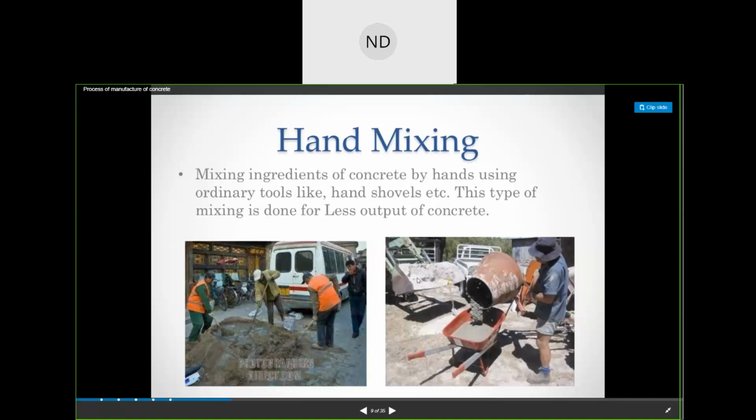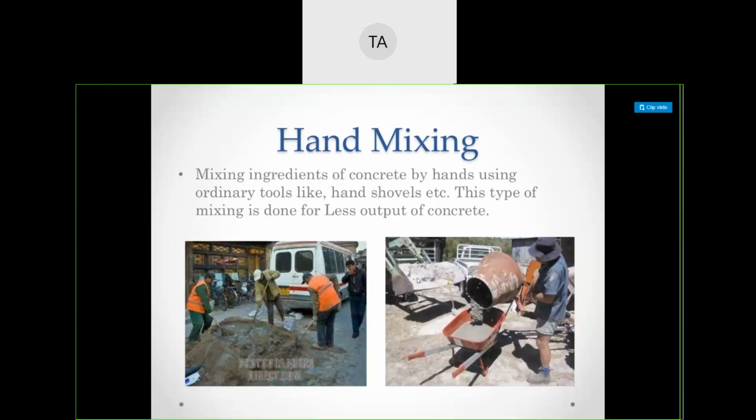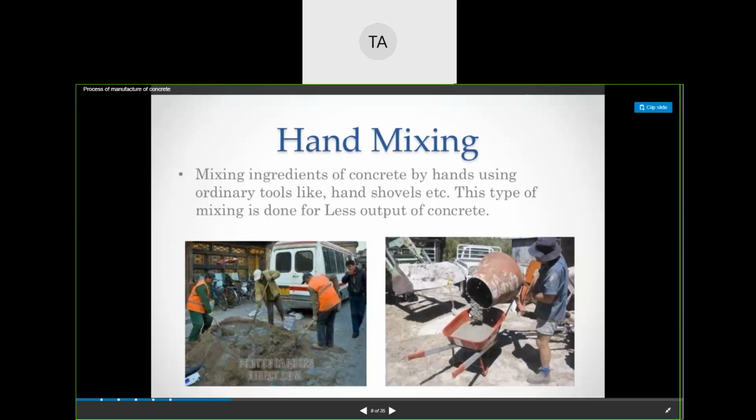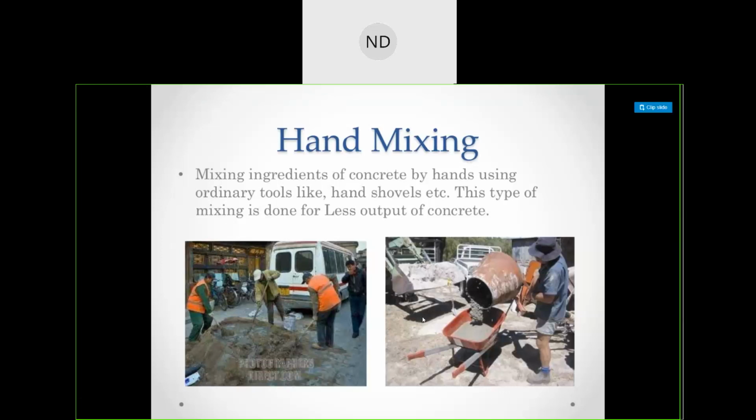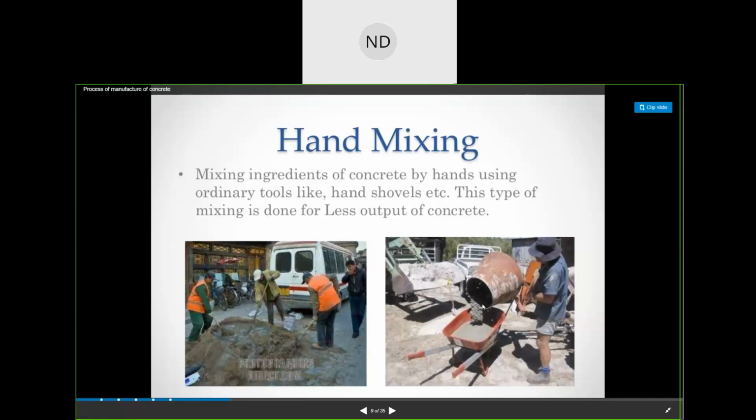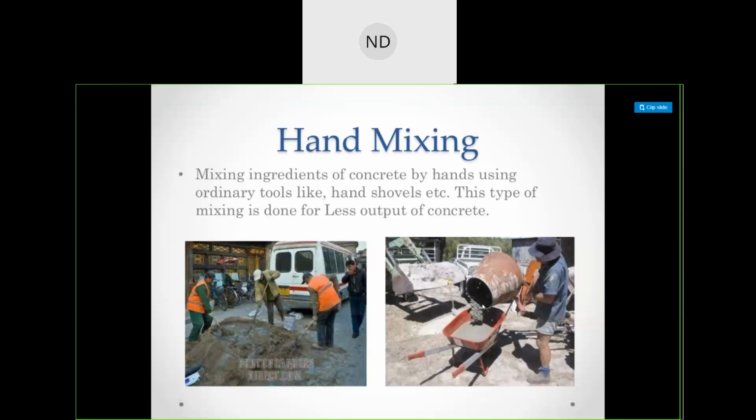Okay, but that means, ma'am, if the concrete is well compacted, then there would be a lower percent of air. Yes, if your compaction is very good, there will be very few air voids. If you don't compact, you just use this concrete which you have mixed here and pour it on your slab, air voids will be present there, and the more air voids you have, the less strong it is, because the more compact your concrete is, the stronger it is.